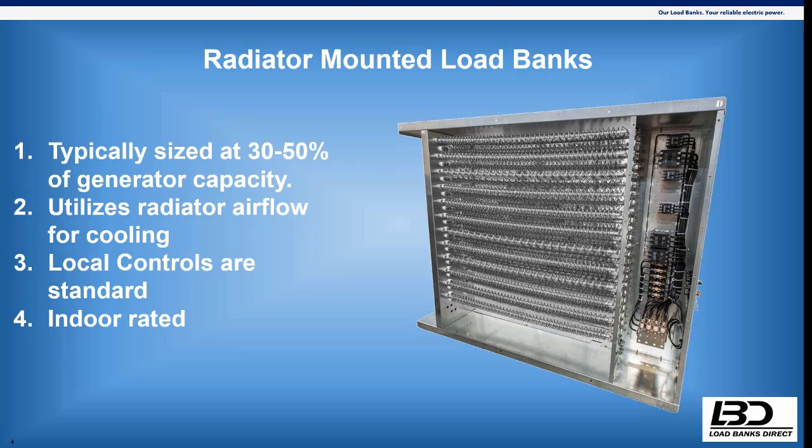They're not self-cooling. They mount on the face of the radiator and utilize the airflow that's being used to cool the generator, blowing through the radiator to cool the resistors as well. They come standard with local controls, typically because they're inside of the enclosure and usually easily accessible depending on the application, but they can be offered with remote controls as well. So you could mount this on the face of your radiator where you can't really get to it, and still mount remote controls inside of the generator control room to operate it.